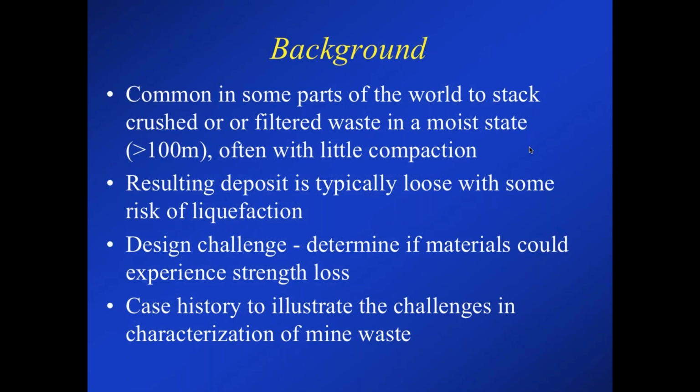So although the material is moist, it's not placed wet, it is placed in a rather loose state, and the resulting deposits are typically loose. Some of these areas are high seismic areas, and so one of the big design issues is liquefaction. Certainly one of the design challenges is: is there a risk of flow liquefaction? Could the material actually experience some strength loss if triggered by an earthquake?